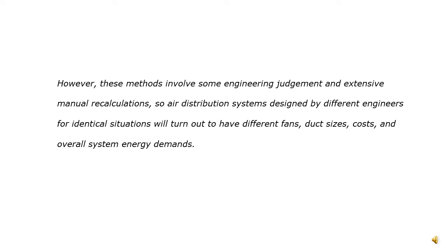Alright, whatever method you use, it requires some engineering judgment and extensive manual recalculation. So you cannot say that your system is better than other engineers' for an identical problem. You may have a different solution than other engineers, and the result is you will have different sizes of components, different fans, different duct sizes, which will incur different costs and also different overall system energy demands.